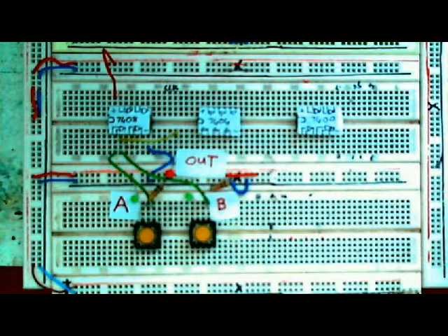For this reason, all inputs must be given a definite high, plus 5 volts, or low, 0 volts, and not left floating, where they basically act like little antennas picking up random voltages from the air, causing them to switch between states rapidly.